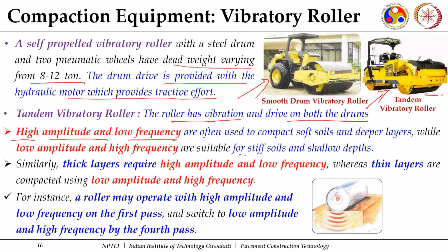On the other hand, if you have stiff soils and shallow depths, you will prefer to go for lower amplitudes but higher frequencies. You can control the amplitude and the frequency of these vibratory rollers. So, this is a very important part in these vibratory rollers.